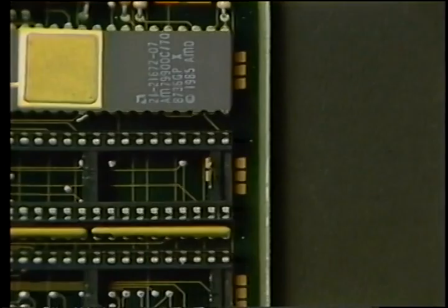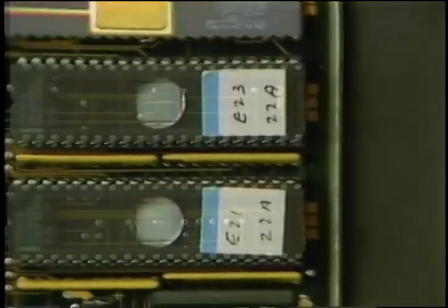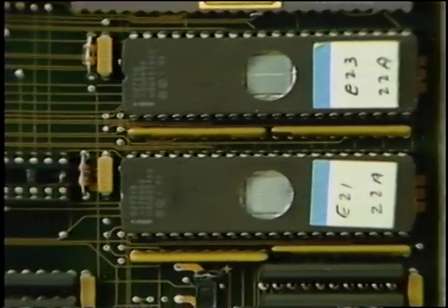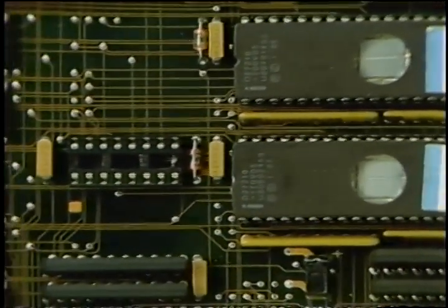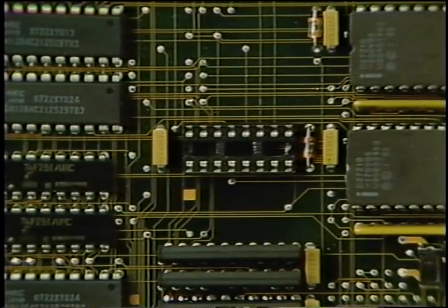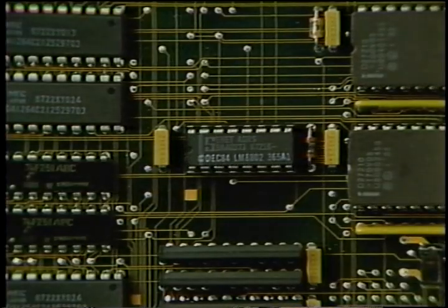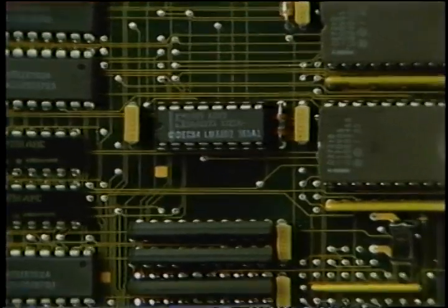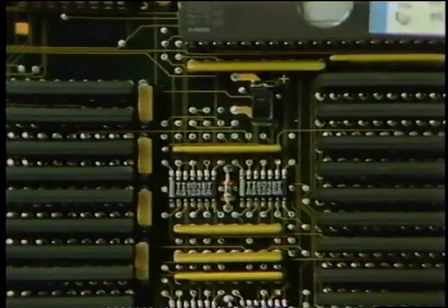Removable base system ROMs contain firmware for boot and console codes, power-up and extended diagnostics, system exercisers, and utilities. Also removable is the Ethernet address ROM, which should be inserted on any replacement KA42 when the system is attached to a local area VAX cluster.